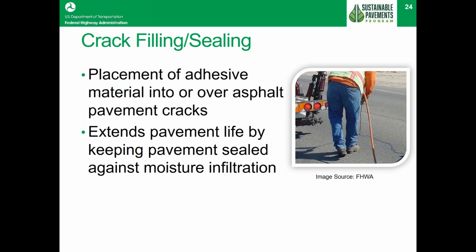So the first of the treatments is the relatively easy one. These are low cost. It's actually a little bit more of a crossing over between maintenance and preservation. The process is not too hard, usually not too expensive, but it is important that it be done correctly. And being done correctly means that the pavement crack needs to be cleaned out before you put the material in there. Typically, these materials are either a hot applied asphalt or some kind of a silicone rubber material that goes into it.